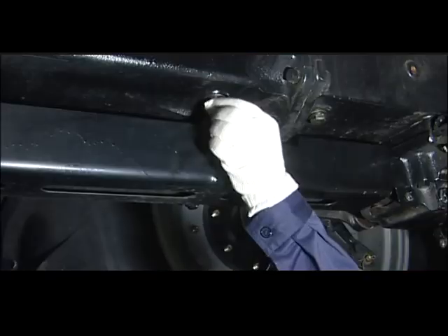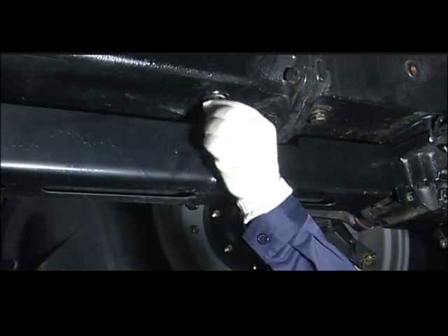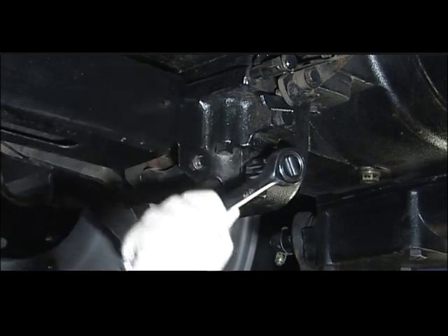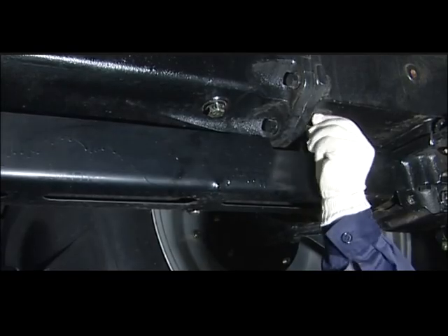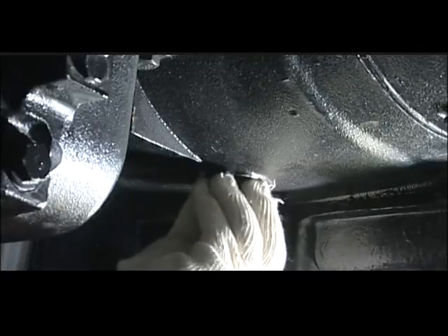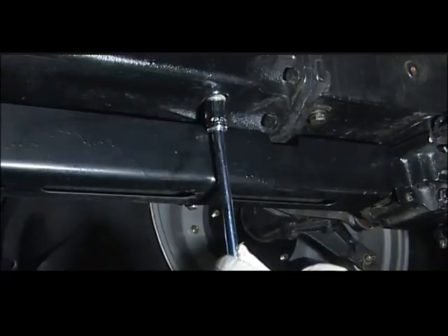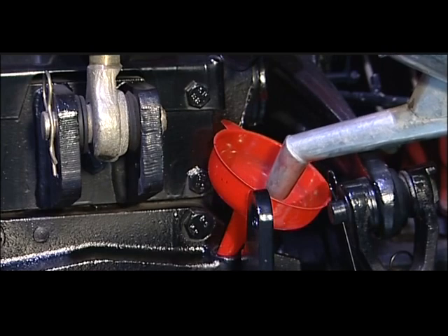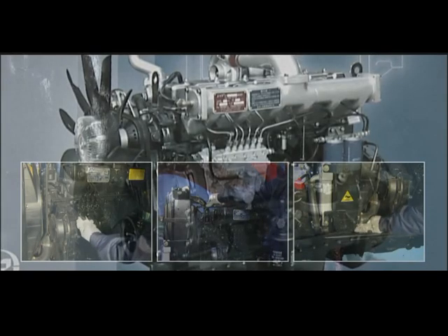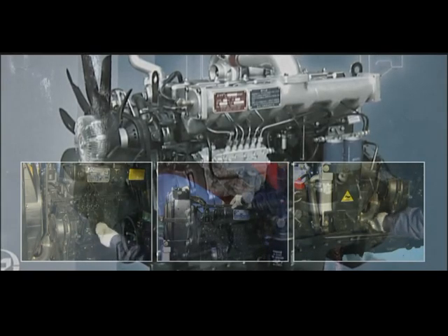When changing the lube oil, remove the front transfer box oil drain plug, transfer box drain oil plug, rear transfer box oil drain plug, and left-right brake oil drain plug. Drain all used oil while it is hot. Retighten the plugs. Refill with new oil. Maintain the engine according to the manual.